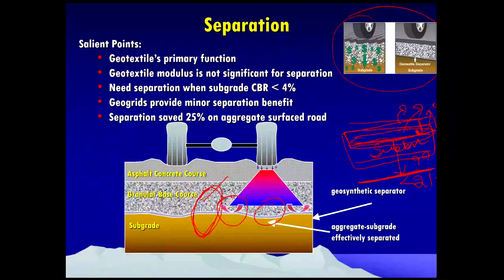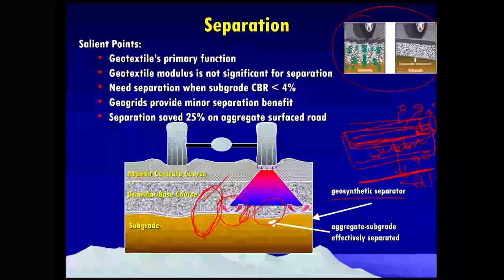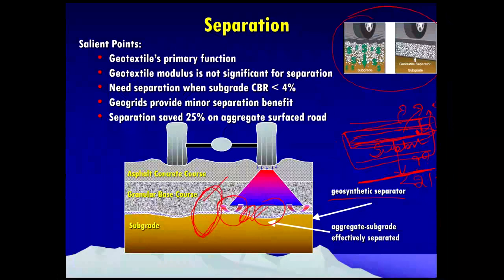It is recommended to place a geosynthetic separator, a porous textile, in the flexible pavement between dissimilar materials. When you place a geosynthetic material between two dissimilar materials, we expect that the integrity and functioning of both materials remain intact, or that the performance can be improved.